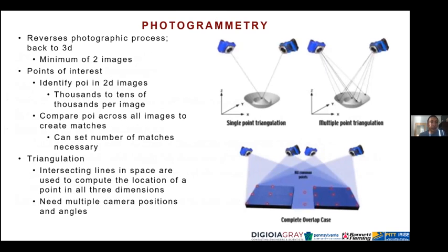So what is photogrammetry? When we take a single photo of our world, we remove that third dimension. We create a flat photograph. So in order to restore that depth, photogrammetry allows us to, if you take 2 or more photographs of the same object from different angles, start to get that depth of field back, restore that 3D quality. And if you multiply this by 1,000 or 10,000 times on a large outcrop, now you can create big 3-dimensional point clouds in true color, and it really creates what I was calling before the digital outcrop.